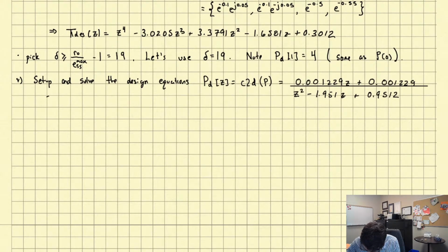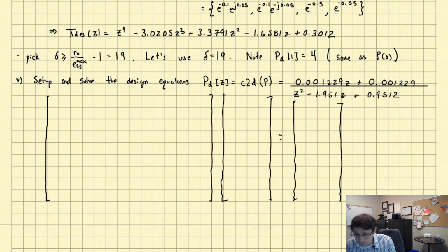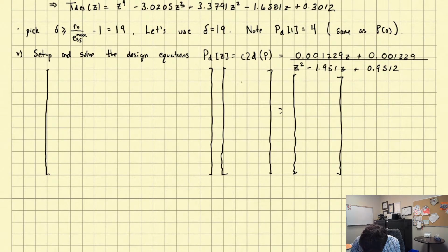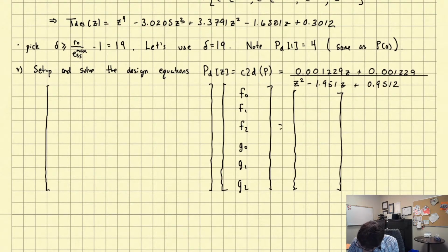Let's write these big equations. I'm going to leave myself a bit of space because these numbers have a lot of digits. Okay. So we want to solve for the controller gains. So the gains are... okay. On the right-hand side, this vector over here, we get that, at least the first part, from our desired characteristic polynomial. And so I'll fill that in. I might not have left myself enough space, but let's just write it this way.